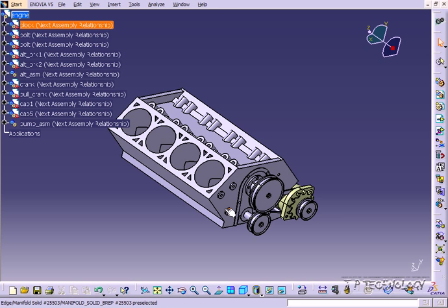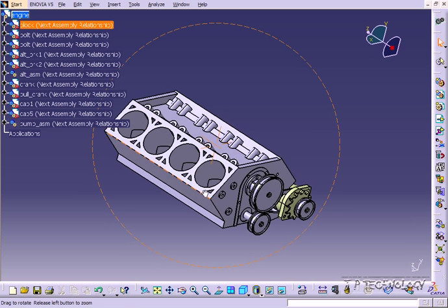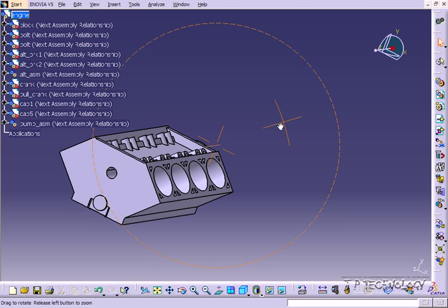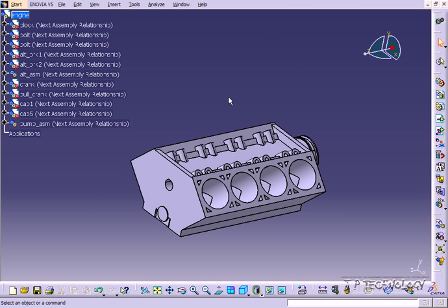And again, I can't emphasize enough how important this is, because if I didn't have an axis there, you're going to get different results every time. To be precise and consistent every time, create the axis that you want to rotate about. You can use an edge too, but if you want to rotate through, say, a circle, get that center circle's axis in there and rotate about that.